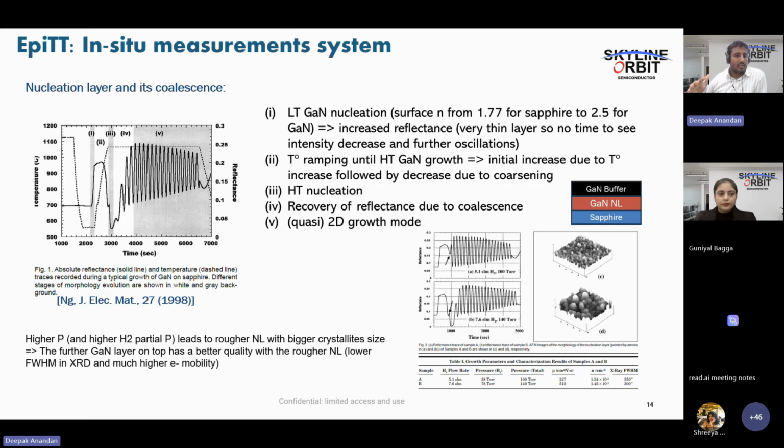One is the reflection from the interface and the substrate, and another one is from the top surface and the air layer. So there are two different interfaces where you can always calculate the path difference. The signals can be either added or subtracted, so that you will have oscillations. These oscillations help you to understand the thickness of the layer.